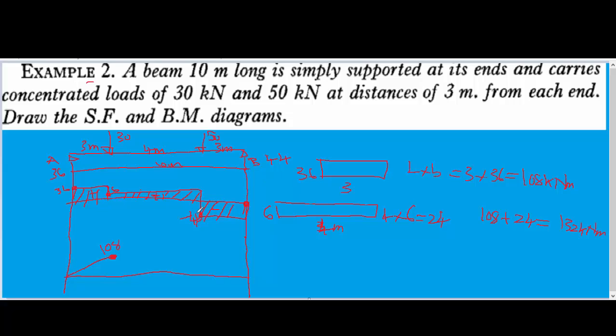So we'll move to the last part, which will also have a rectangular nature. Also we have minus 44 as our breadth and 3 meters as our length. So in this case we'll have our length times breadth. Our length is 3 meters, so we have 3 times the load, 3 times minus 44, which is equal to minus 132.